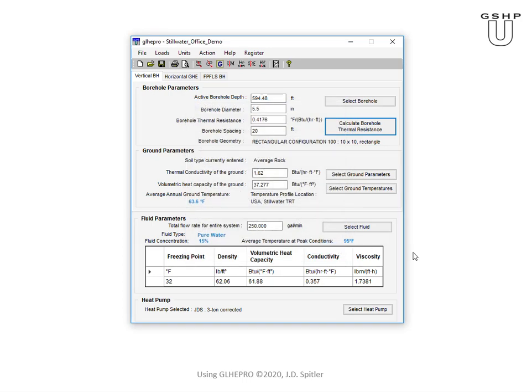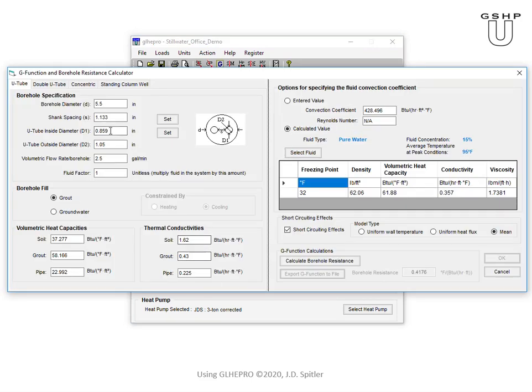Okay, so the first thing I'm going to suggest is that our borehole design is not a particularly state-of-the-art one. So if we go back here, it may well be that if we use standard piping, this default value for the conductivity of HDPE is reasonably good, but this and the soil conductivity we're pretty much stuck with, but the grout conductivity, we could enhance that. Now, in the early days, I think I mentioned one of the first thermally enhanced grouts is called Thermal Grout 85, if I remember right, but it had 0.85 conductivity.